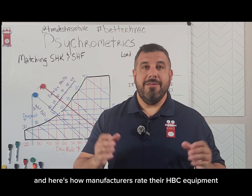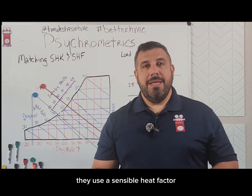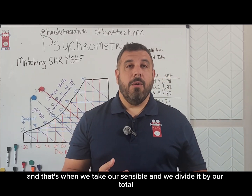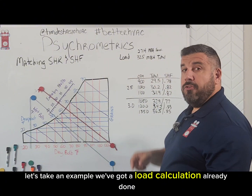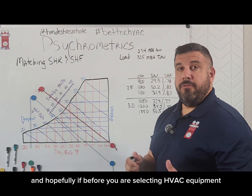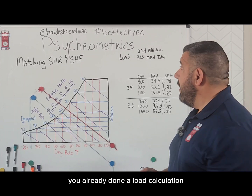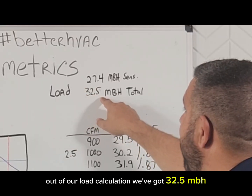And here's how manufacturers rate their HVAC equipment. They use a sensible heat factor, and that's when we take our sensible and we divide it by our total. Let's take an example. We've got a load calculation already done, and hopefully before you are selecting HVAC equipment, you've already done a load calculation. Out of our load calculation, we've got 32.5 MBH.